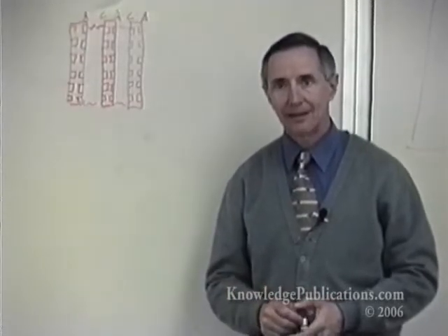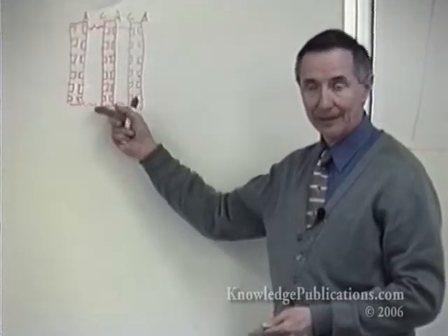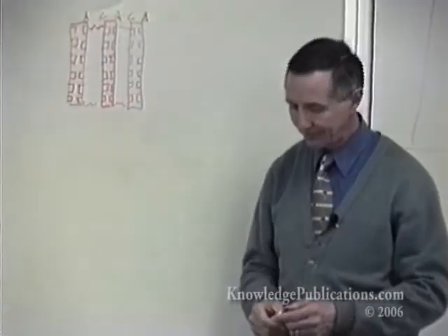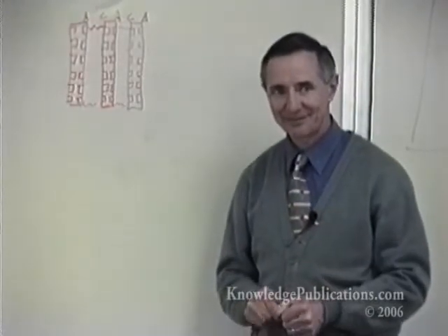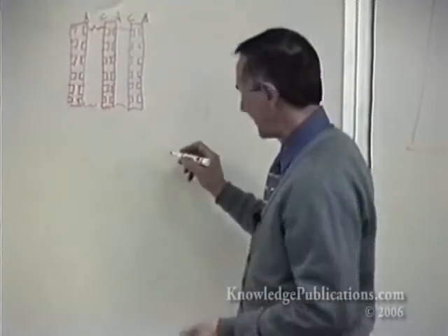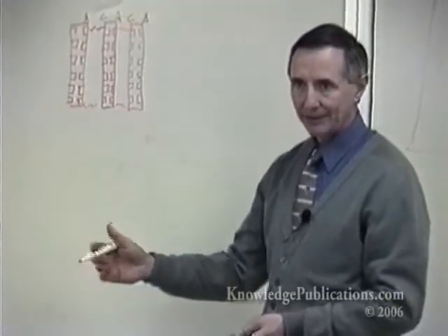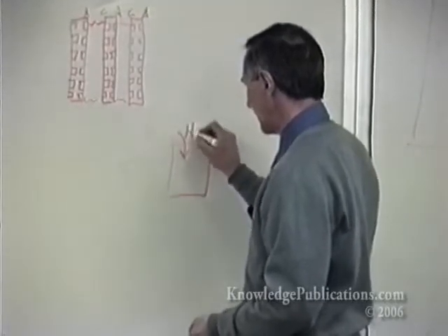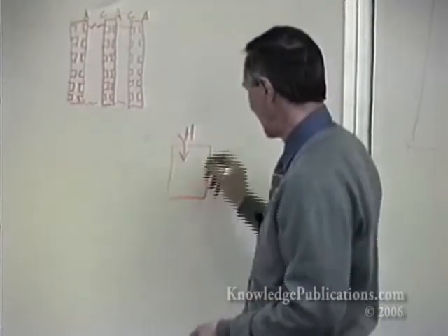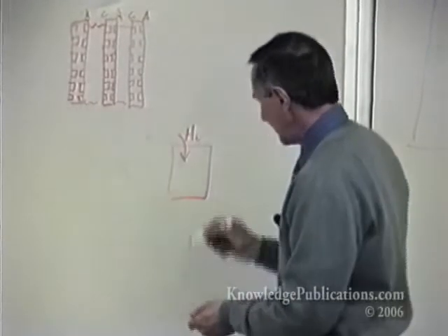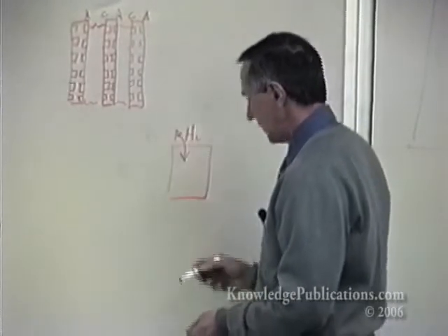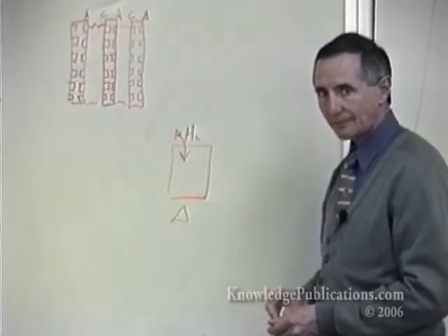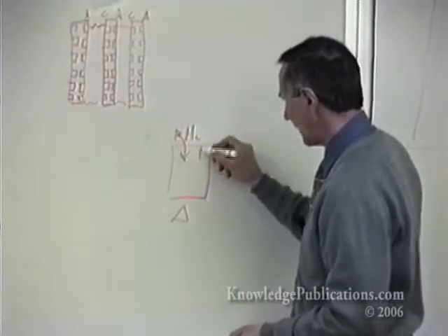Well, for cooling, there are a number of cells you could run. One is a hydrogen hydride heat pump. Here's how it works. Glad you asked. There's a type of heat exchange system that's based on a first reservoir of hydride. You add hydrogen to it at ambient pressure or some low pressure. Then you close the valve or run it through a check valve and heat it up. You add 80-degree heat. It then gives you hydrogen at high pressure.